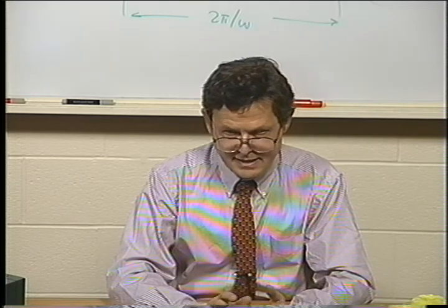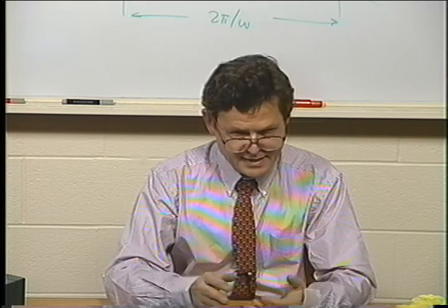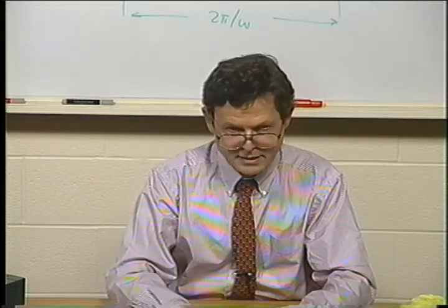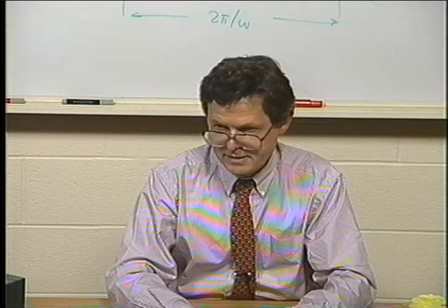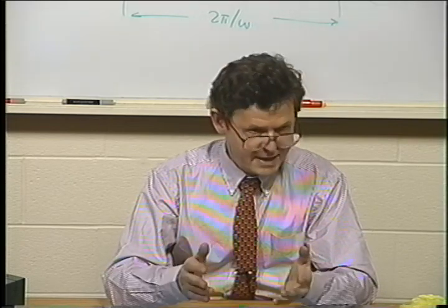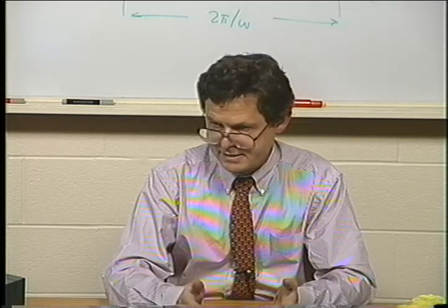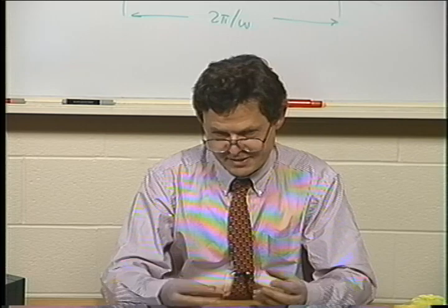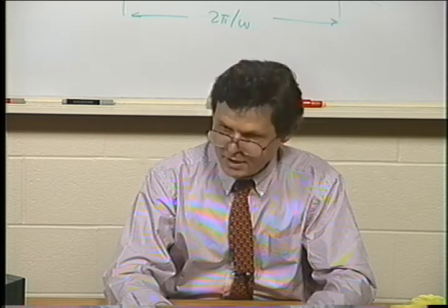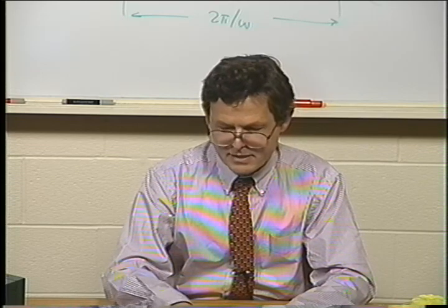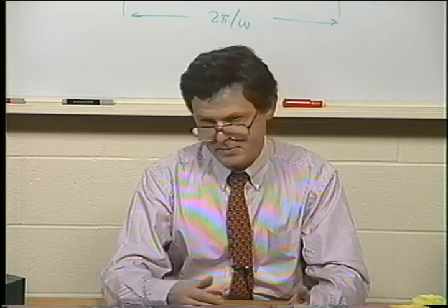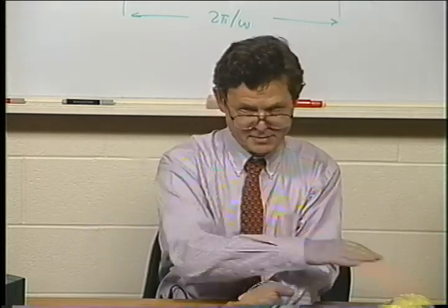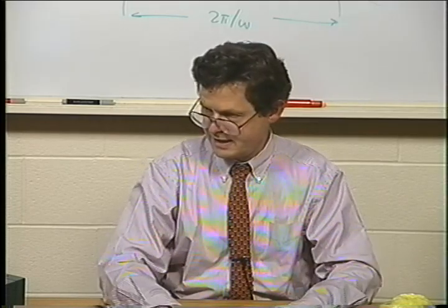And you can see that for quantifying elasticity, we are talking about a time constant of the material, the time the material needs for relaxation. And elastic experiments always require a time scale short enough so that the material has a memory, hasn't forgotten the history which would give rise to those elastic effects. Or if you have a material which has a relaxation time which is short enough compared to the processing time, or if you process it at long times, like a steady load on my bouncing putty, then it flows and you don't see any elastic phenomena.